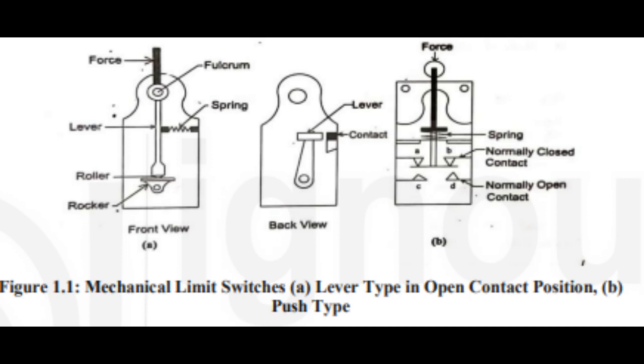They are sometimes used in materials handling applications, e.g. to indicate the passage of a part along a conveyor. They are typically designed to handle relatively high voltages, both AC and DC. This means they cannot be directly wired to the input port of a computer without having their signal converted to TTL level.